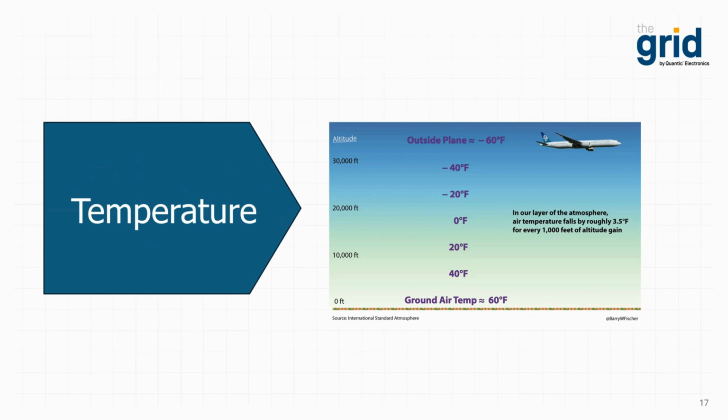Different capacitor technologies have different temperature ratings, so attention must be paid to the capacitor's operating temperature range during selection. Some also have significant performance variation as their ambient temperature changes. For example, some capacitors have much lower capacitance ratings at cold temperatures and can lose half or more of their nominal, or room temperature, capacitance at extremely low temperatures commonly seen in avionics applications. Accounting for the worst case scenario in low temperature environments is a key part of the capacitor selection process.